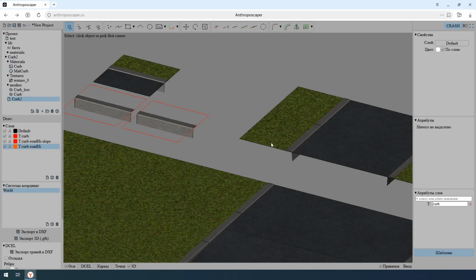Where the road runs flush with the grass, a tall curb isn't needed. A low one is called for in that case. And a tall one is appropriate exactly on the descent at the transition of levels. So we need two variants in one family. First, I make the proper road high grass template with a low curb. This is the general case. It applies everywhere the raised road borders the grass.